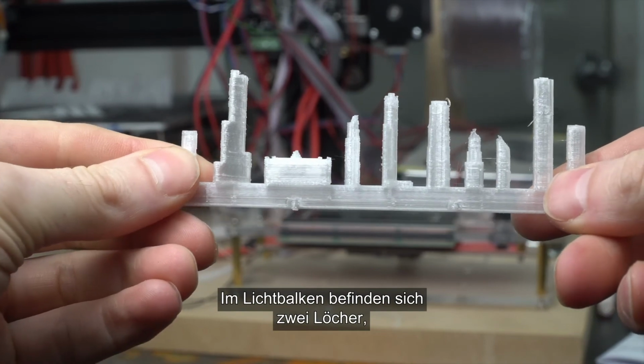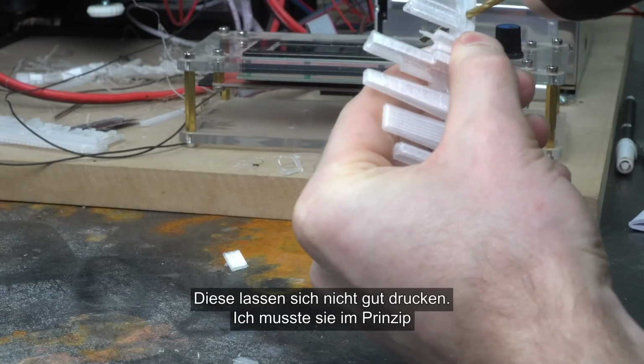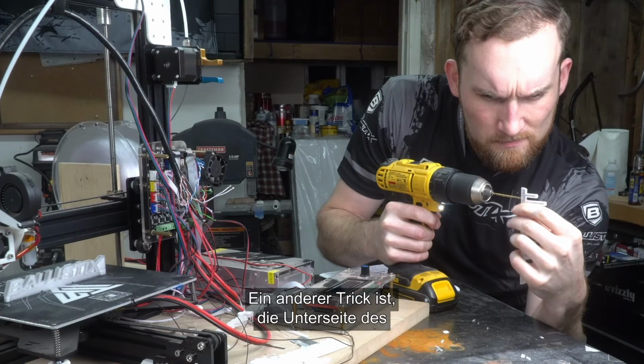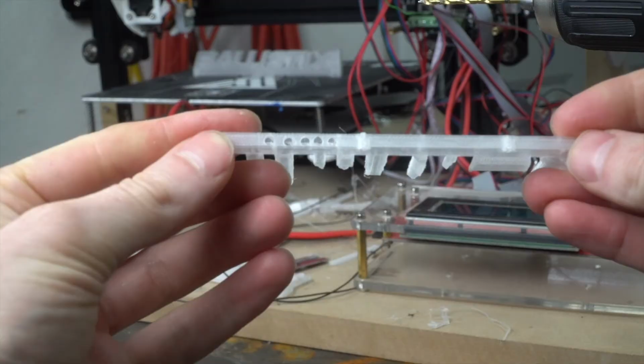Now at the light bar, there's 2 keyholes to keep the pieces from moving around. These don't print really well, so I found I had to pretty much drill them out to make them usable. Another trick I found is actually drilling out the bottom of the light bar. This helps with the LEDs just so there's less obstruction.